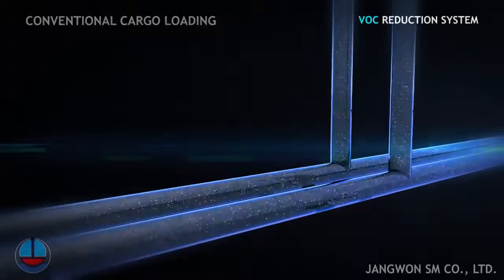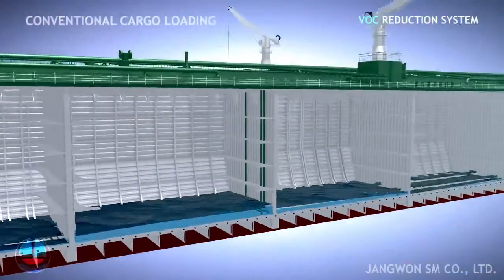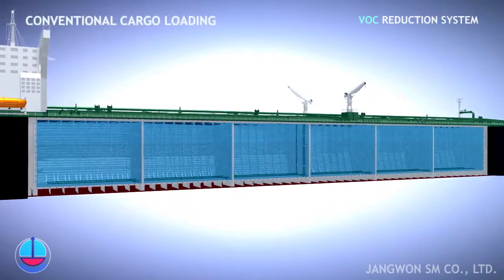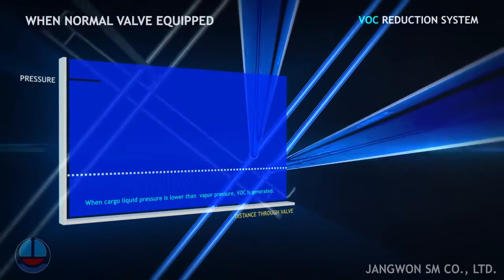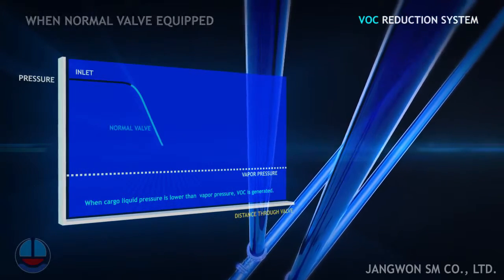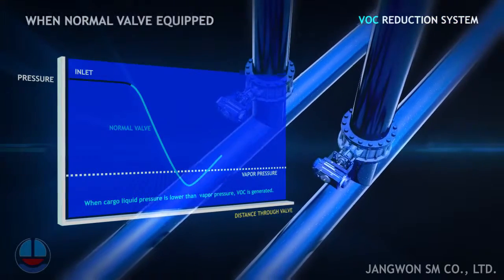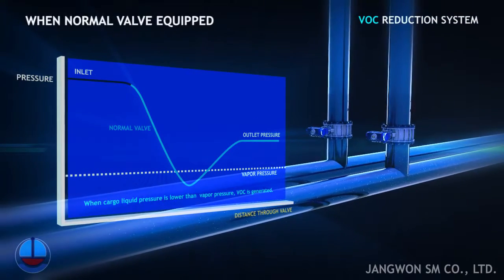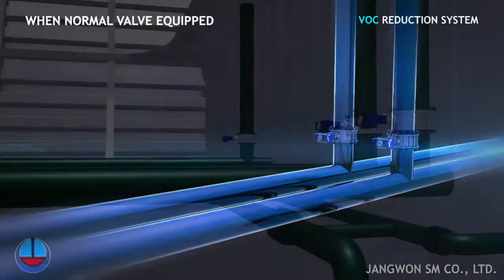Hence, we came to believe the elimination of the vacuum condition could be a key solution to restrain VOC generation. The vacuum can be eliminated by installing flow control devices at the bottom of drop lines. However, a significant amount of VOC is still generated in most flow control devices when cargo passes through the devices. For this reason, we have developed a special VOC suppression device, called the anti-cavitation valve.